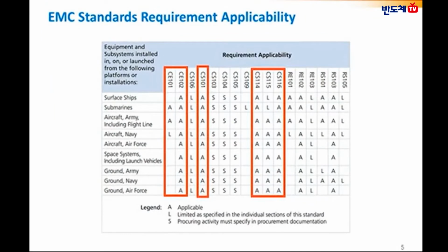Similarly, the transient immunity or the electrical power characteristic requirements are documented in MIL-STD-704F or MIL-STD-1275D or E. The transient immunity is the ability of the system to withstand any sudden change in the input voltage. And such transient immunity characteristics are documented in the MIL standard reference documents.